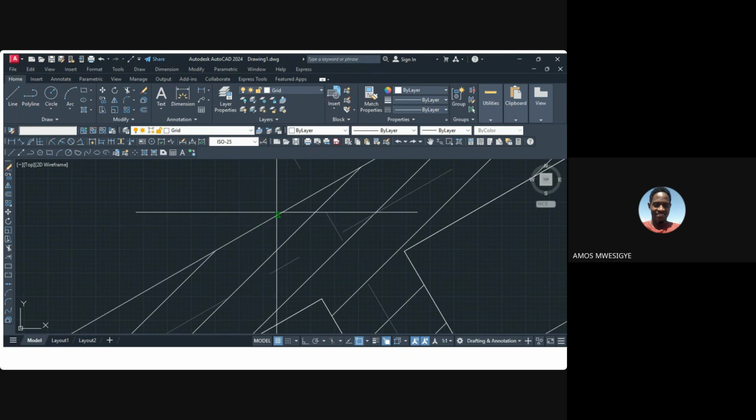By the way, what I'm doing here, we looked at this last time. These are green things, those small things you're seeing. It is called the object snap, snap cursor. It enables you to see perpendicular. In other words, you're spanning within the object. So it can enable you to see the endpoints, midpoints, center, geometric centers, all these.